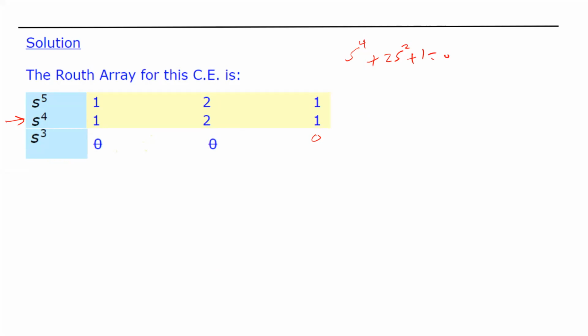Look, when you have the characteristic equation, you put 1, 2, and 1. So it's going to be s to the fifth, s cubed, and s to the 1. Now you alternate. So this is basically the polynomial which you have. And we said then I will differentiate. Okay, this is the auxiliary equation. You differentiate the auxiliary equation. If you differentiate, this is what you'll get. Take the coefficients and put them here.